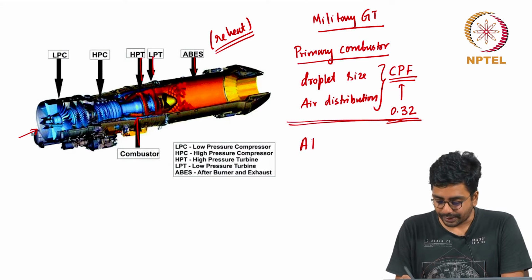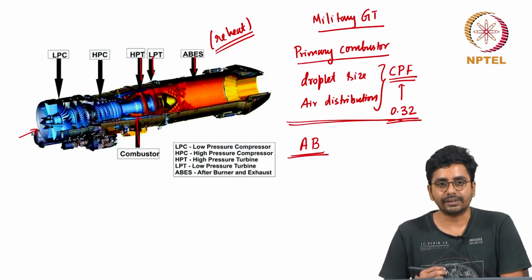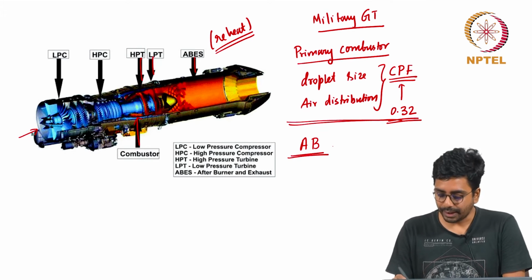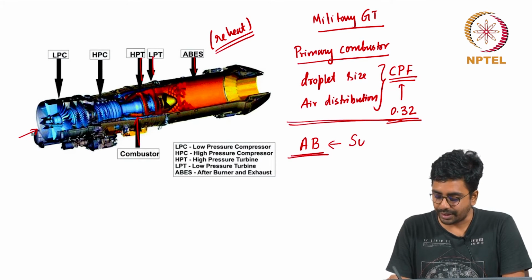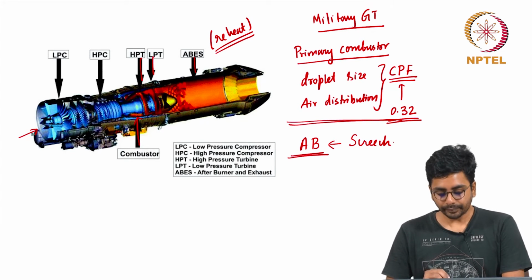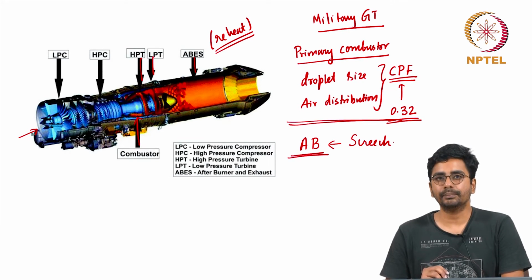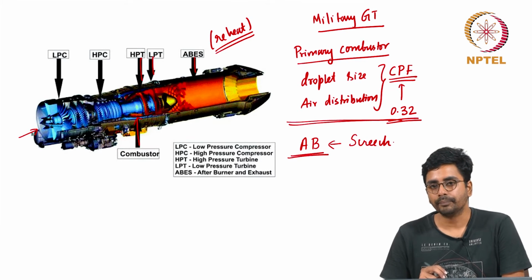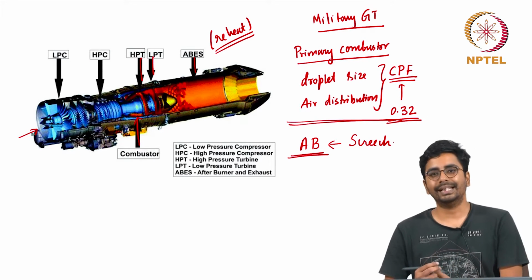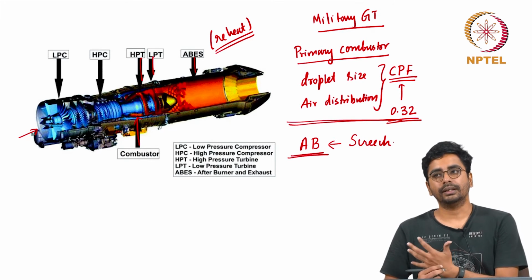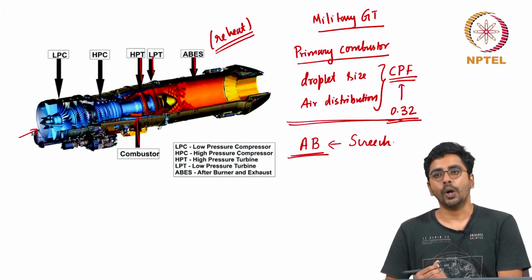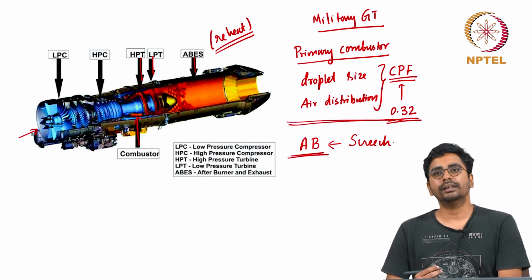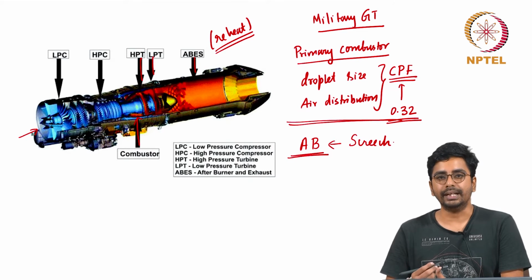As far as the afterburner is concerned, okay, again the fuel is injected as a spray in a much simpler form as compared to a primary combustor, but here the problem is one of acoustic instability called screech. This is a high frequency acoustic instability, and here again the principle that lateral non-uniformities must be minimized to avoid coupling seems to be valid. Remember that in the liquid propellant rocket instability problem, it appeared like ensuring lateral homogeneous mixture fraction distribution aids stability. Here again, avoiding lateral non-uniformities seems to aid stability.